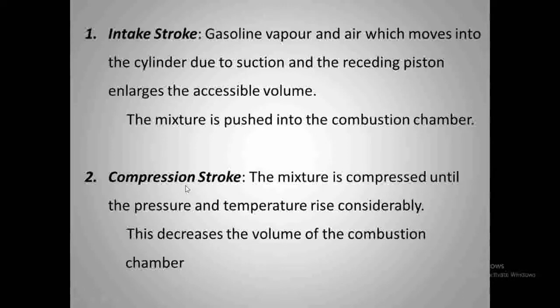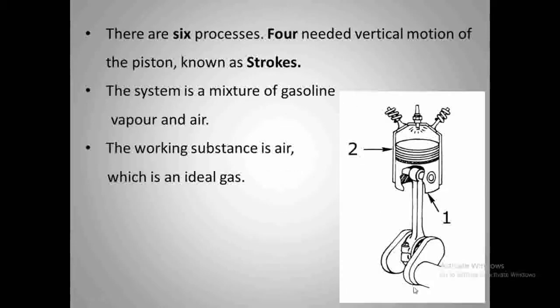The second one is the compression stroke. Compression stroke means the volume of the chamber will be reduced. How can the volume be reduced? We can move the piston inward, then the volume of the chamber will reduce, and that is the compression stroke. Stroke means the movement of the piston either inward or outward.